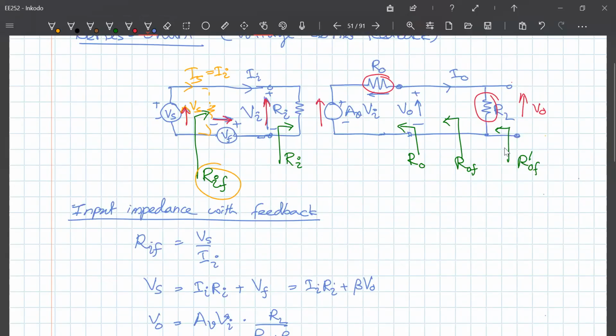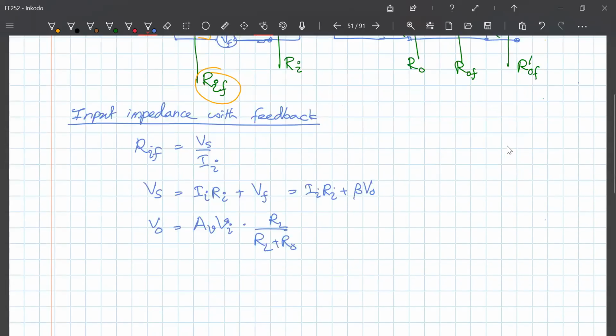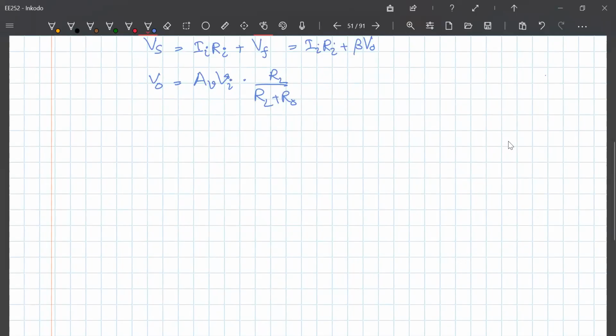Right, so this is basically I have this voltage applied across these two resistors. The current is the same that is flowing through these two resistors, so therefore there is a voltage division that I can look into. So V out can be written as V out is equal to RL over RL plus R out times this voltage here. Okay, so that's this.